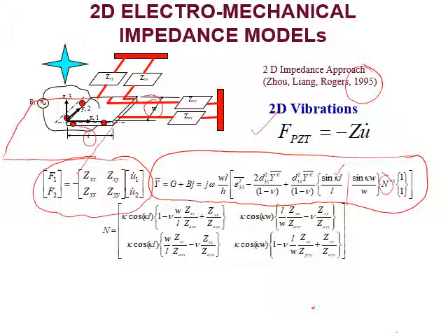So can we use this equation to obtain these impedance terms? Because what we get from experimentation, we get two measurements, G and B. So can we use these set of equations? So totally we have two set of equations, but how many unknowns are there? Total 4 complex unknowns. Each has the real part and the imaginary part. So total there are 8 unknowns. So 8 unknowns cannot be obtained by just using two equations.